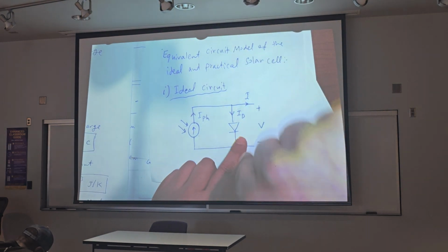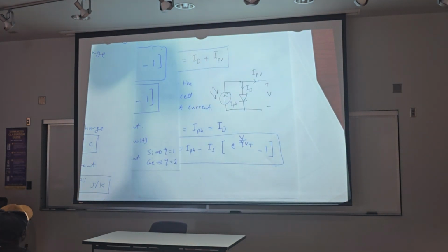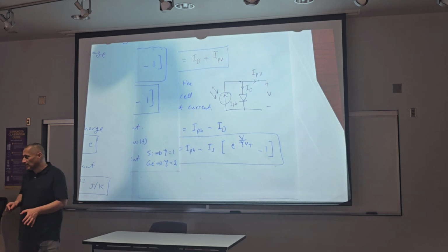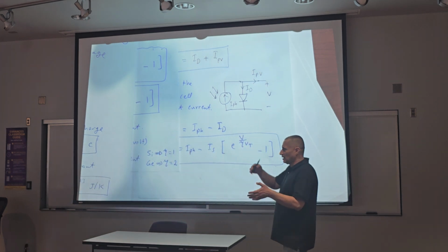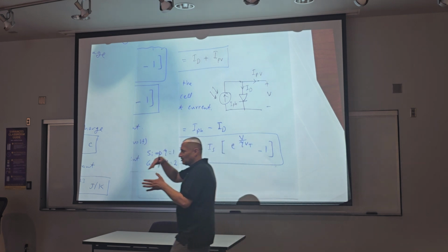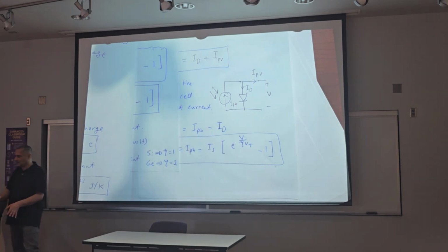Does V_T exist in any diode or only because we're dealing with solar? At 300 kelvin temperature, because the other terms are constant, and we suppose room temperature 300 is equal to 26 millivolts, for silicon and for germanium, the same.